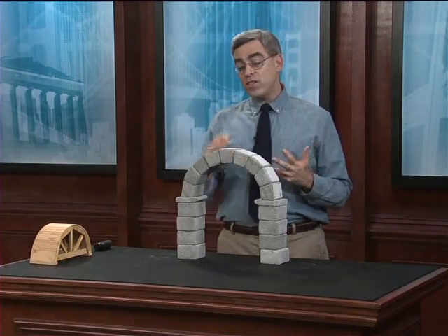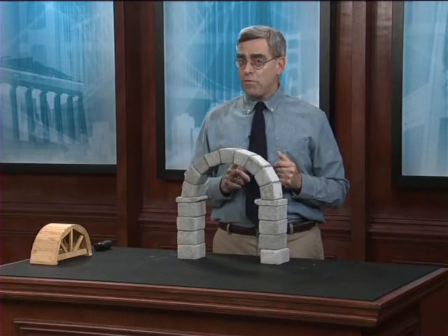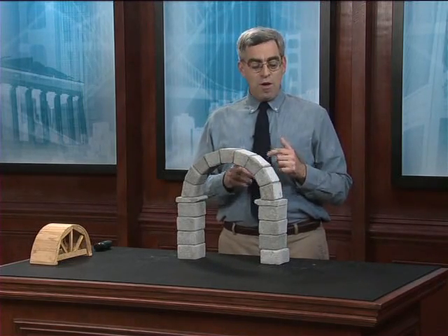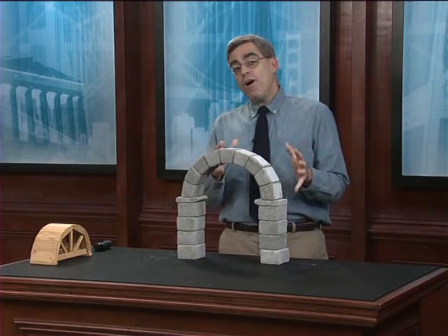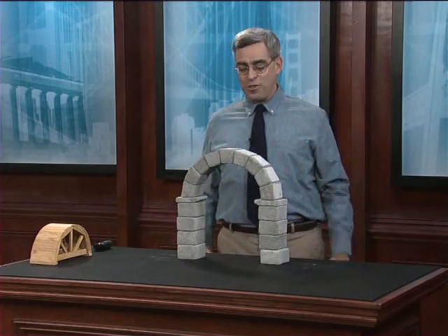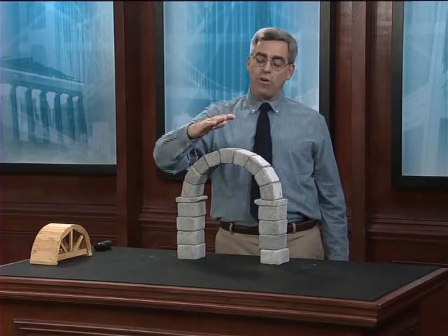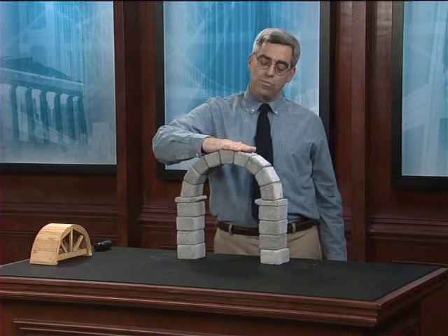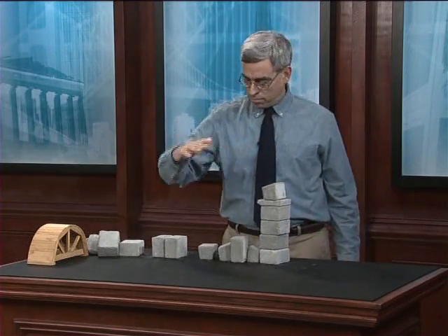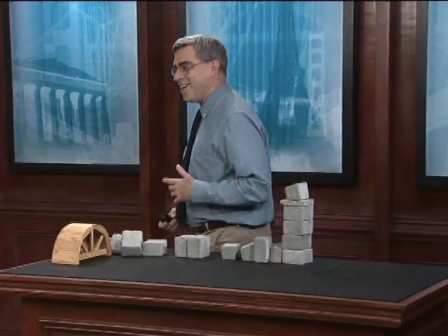What that would suggest is that this arch is probably not capable of carrying very much load. It's actually probably pretty well through the process of failing due to instability. And so if I add just a little bit of additional load on top, it may very well collapse. Let's see how that works. Indeed it did. Very clearly, when a single arch is placed on top of two columns, the outward thrust of the arch tends to cause those columns to overturn.